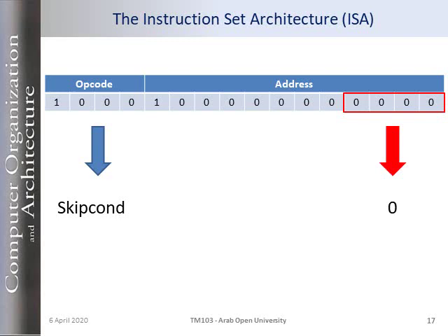If you want to get the equivalent number in hexadecimal from binary, to convert from binary to hexadecimal, we will divide our 12 bits into 4 bits, 4 bits, 4 bits, and then for each group we're going to get the equivalent hexadecimal number.